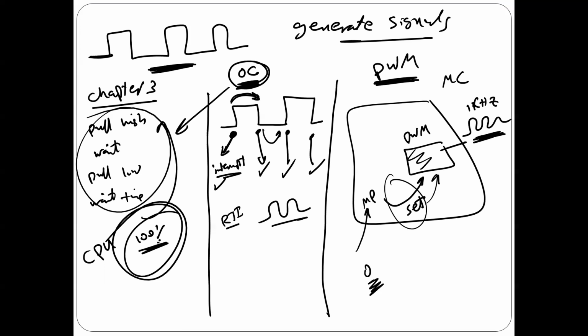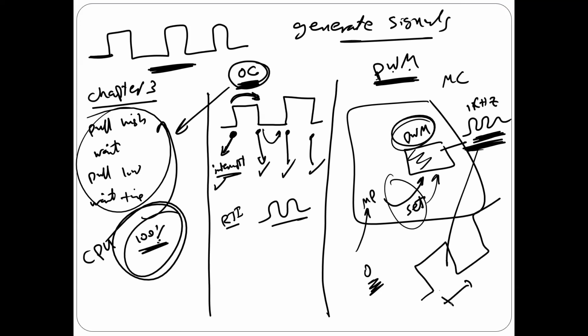This is not only that. In pulse width modulation, from the name, pulse width modulation, you can control the duty cycle easily, as you will see later. Duty cycle, it's very trivial, very easy in programming to control. You know, as I taught before, duty cycle is how much high comparing to the whole.